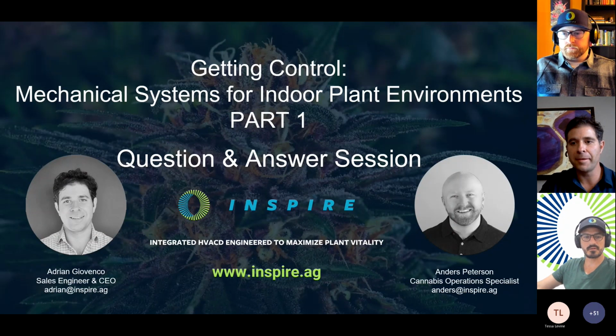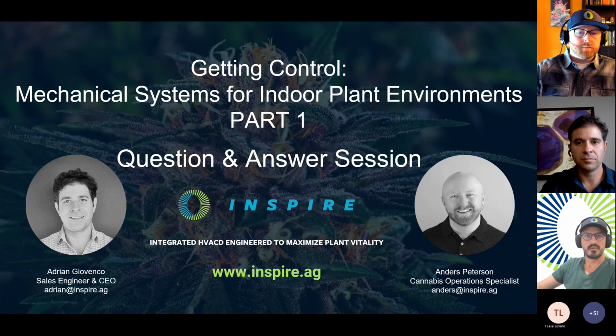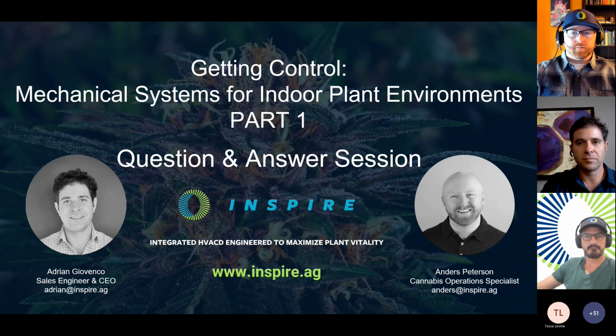Also, choose a good, experienced contractor with a track record in commercial and industrial trades. It's so critical to the operation of your HVAC systems, particularly the way that they were installed and the quality of the ductwork and reducing the static pressure along those duct runs. And we've seen good and we've seen bad, and it can play a very critical role in the performance of your facility, even if the HVAC units are right sized. Yeah, that's really great points.